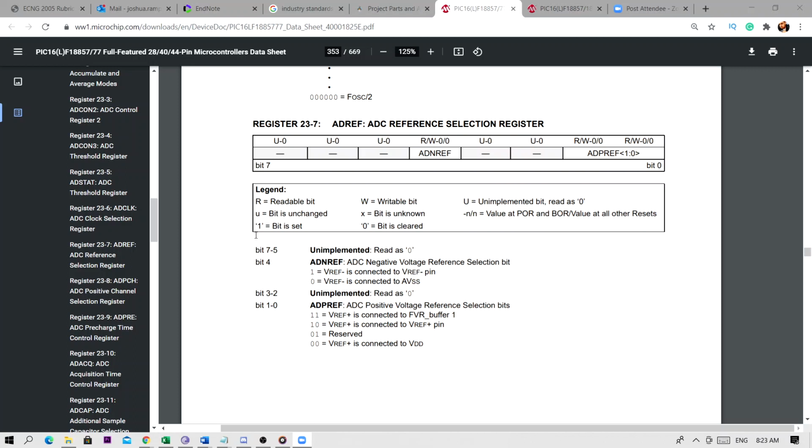So just what I was saying earlier is that we can't convert something at all times, but what we could do is we could take snapshots, right? So I could take a snapshot here. I could take another snapshot here. I could take another snapshot here. In other words, I could take snapshots at regular intervals, right? Yeah. In this case, it's only one channel we're dealing with. We're not changing channels. We're just going to take snapshots of the voltage at various times, okay?